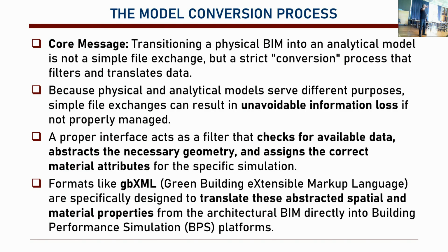So that's important. And of course, there is this model conversion process. This is done in the software. You will also experience that in the tutorial. You basically create an analytical model for energy, for instance. And when you do that, it creates a filter that gets rid of all unnecessary things like the walls, but it uses the walls' data about the U value. Then it's replaced with just a plane, for instance. Okay, that's the idea. That conversion is important.